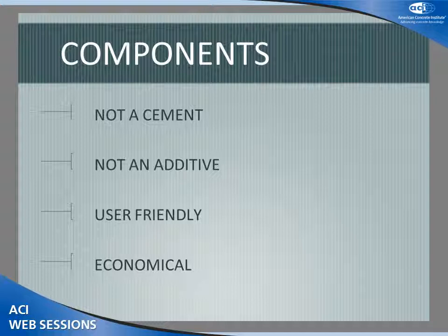The Type G maximum expansion is reached within 48 hours, during the same time period that the concrete experiences its greatest strength gains. Type K concrete, in comparison, reaches its maximum expansion during the third, fourth, or fifth day, and this is after the concrete is hard enough to be placed into limited service.